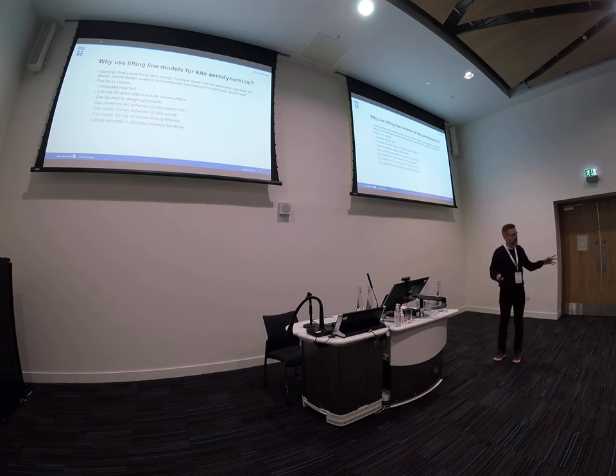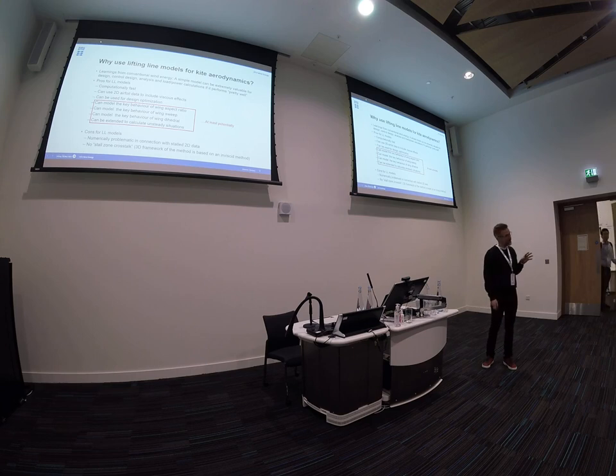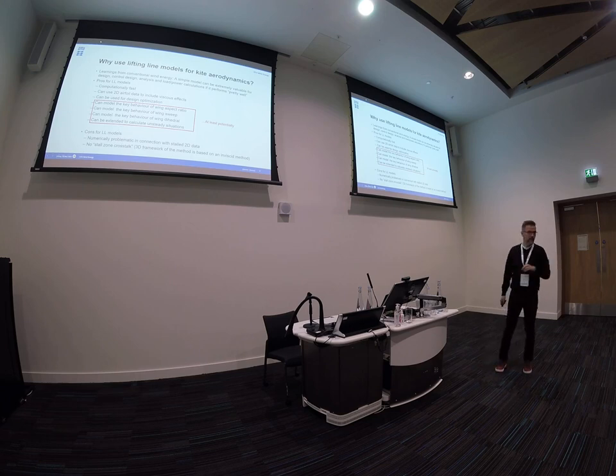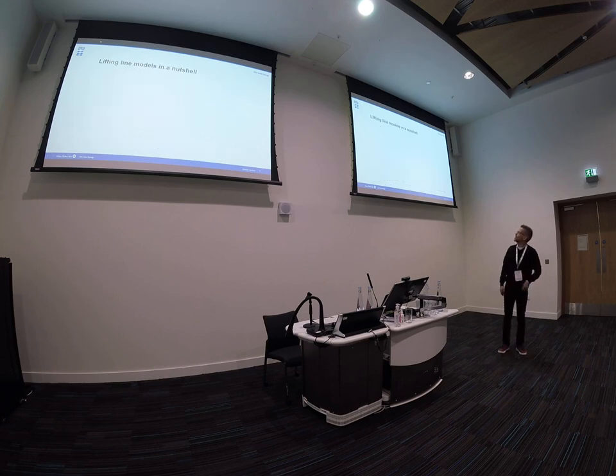You can model the key behavior of geometry, of sweep, dihedral, unsteady situations, maybe if you do it right. And the cons is that there are some iffy things when you start using airfoil data that go into stall. There are some numerical issues when it's hard to figure out that part. So I'll focus on the stuff in this red box here.